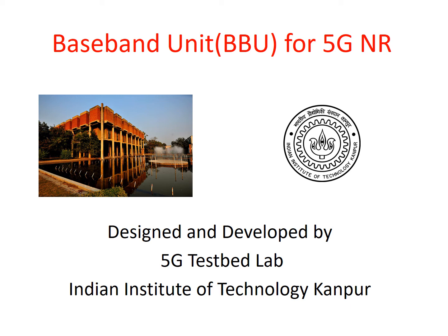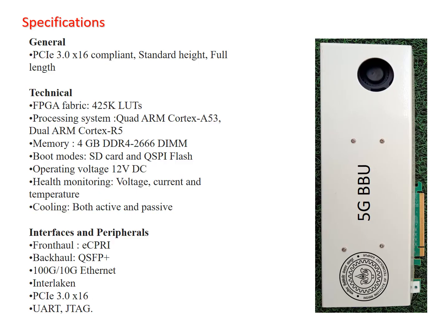5G Testbed Lab at IIT Kanpur is responsible for the design and development of baseband unit for 5G NR. The project is being funded by Department of Telecommunication, Ministry of Communication. On coming to technical specifications, BBU is PCIe 3.0x16 compliant board that can be inserted in a server.